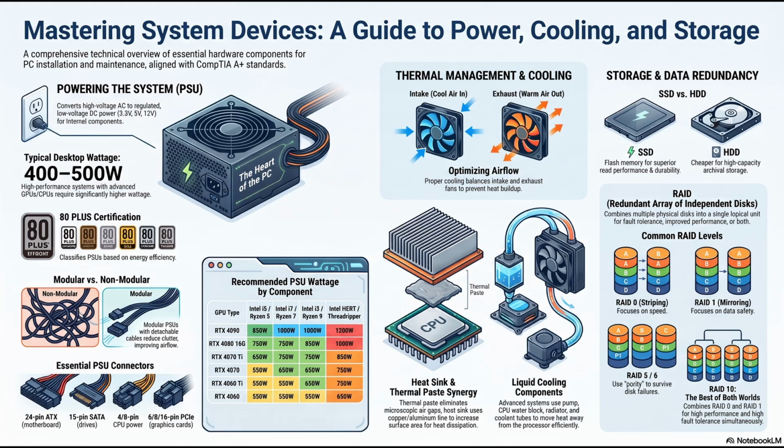To understand why, we have to look at the microscopic architecture. RAM stores data, the ones and zeros, inside billions of microscopic cells, each consisting of a transistor and a capacitor. Capacitor is like a tiny battery. Precisely. If the capacitor holds an electrical charge, the computer reads it as a 1. If it is empty, it reads a 0. But capacitors are fundamentally imperfect containers. They naturally leak their electrical charge over time. Like a bucket with a microscopic hole on the bottom. Yes. So, to prevent the data from fading away into meaningless noise, the memory controller must continuously send a refresh signal, literally thousands of times every single second, to read the state of every capacitor and top off the charge in the ones that hold a 1.